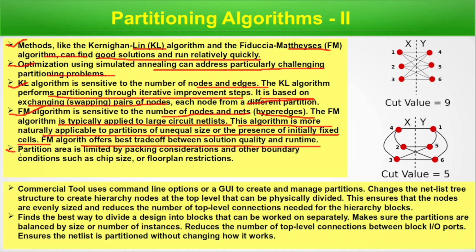Now, partition area is limited by packing considerations and other boundary conditions such as chip size and floor plan restrictions. We have repeated this point because we have to always remember that whatever the algorithm or methodology, we have to be restricted by some constraints like chip size, floor plan, etc. And we have to work within that, keeping cost as low as possible, because everything is for business and high cost is not viable for business.